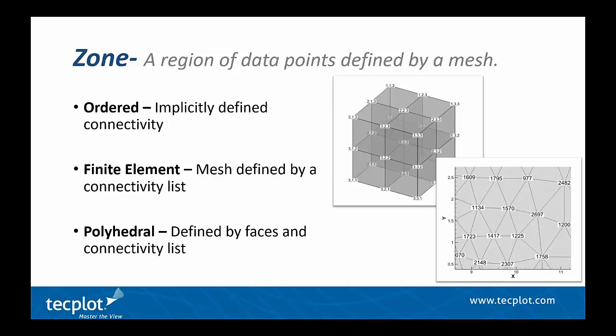So the building block of Tecplot is really the zone. And a zone is a region of data points defined by a mesh. It can be 2, 3, or 1 dimensions. And there are 3 different classes of zones. Ordered zones, where the mesh is implicitly defined by connectivity. This is very similar to MATLAB's matrices in 2 and 3 dimensions.